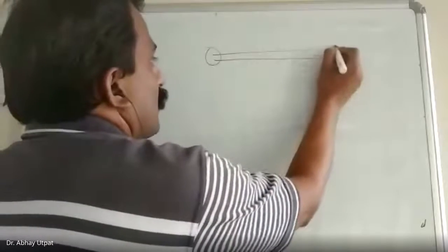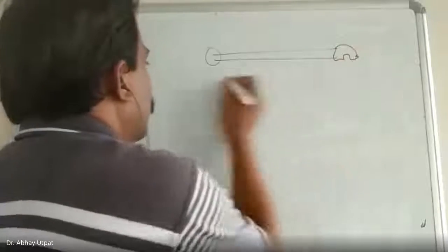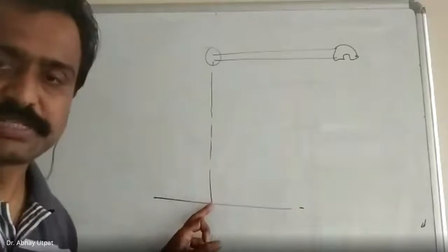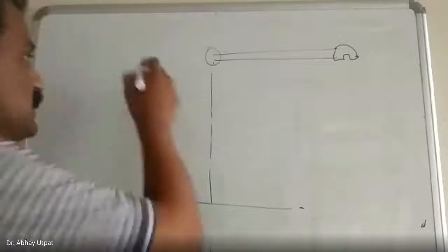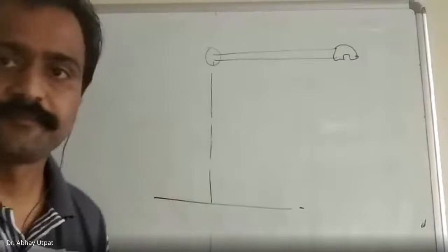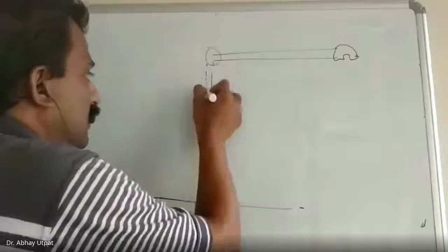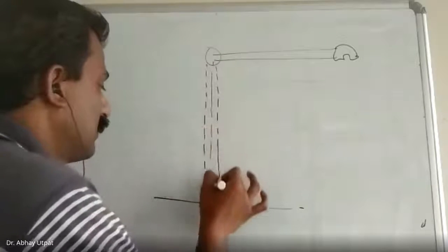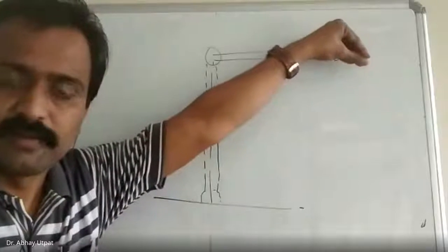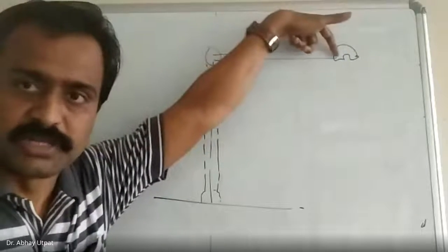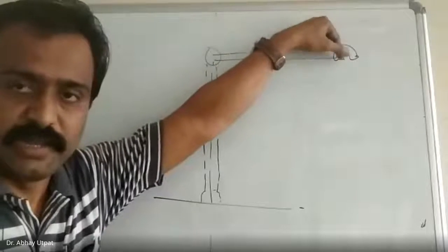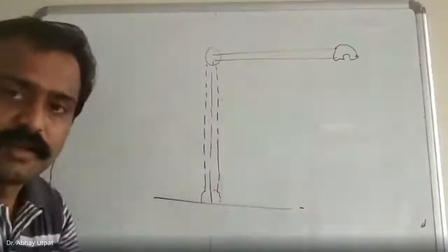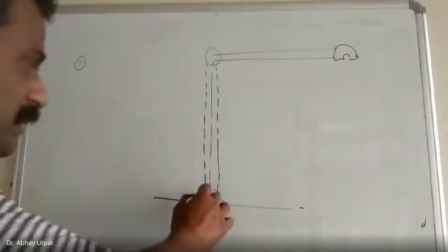This is the original position of the hammer. I have shown this hammer. The specimen is kept here. Now, case number 1. This hammer will remain here itself, once I leave it. It is locked originally. When I am going to start the machine, I have to remove the lever. It will immediately come down because of its weight. And in case number 1, I told you, it remains vertical.